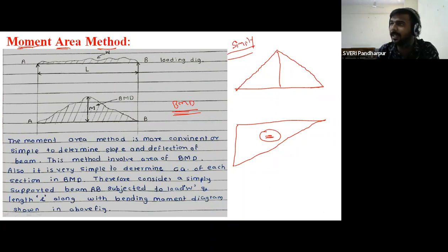And whatever diagrams we have drawn for the simply supported and the overhanging beam, the maximum diagram is present in the positive region, and from positive it goes back to negative. That means we get a point, the point of contraflexure, where the shear force becomes 0. But such diagrams we cannot use for the slope and deflection derivations.